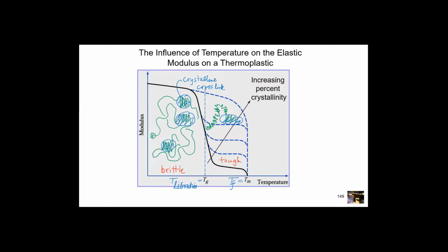And that means that if I hit this polymer with a hammer or something, I can excite all of those motions, those degrees of freedom for motion, and use them to dissipate the energy. Whereas if I try that at a lower temperature, below TG, I hit it with a hammer, it's just going to snap and break. We'll break some bonds and it will break.